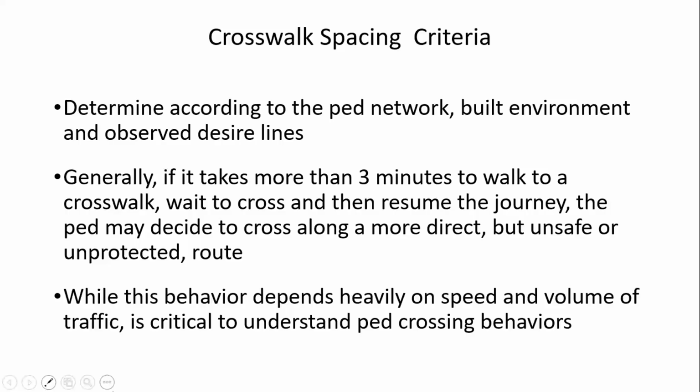I think NACTO says generally if it takes more than 3 minutes to walk to a crosswalk, to wait to cross, and then to resume the journey, the pedestrian may decide to cross along a more direct, maybe unsafe or unprotected route. While this behavior depends heavily on speed and volume of traffic, it is critical to understand pedestrian crossing behaviors.